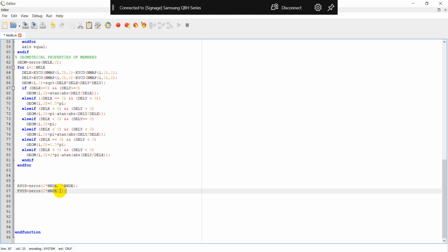But in general, when we talk about more advanced structural analysis, the structure gets larger and larger. In one building, it will take time to construct the stiffness matrix, and that is the cost. So if you have many load cases, then you just construct K once, right? And then the load cases are solved by just changing the force vector, and you invert that stiffness matrix just one time. So that's up to you, it's up to the number of load cases we have.